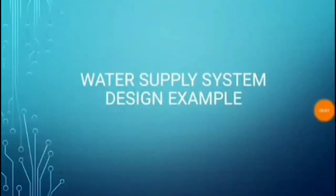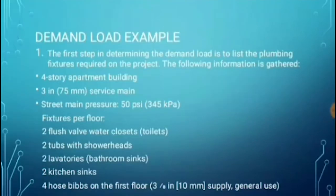Water supply system design. Demand loads consist of three steps. First, we need to determine the demand load by listing the fixtures. It includes a 4-story apartment building, 3 inch or 75 millimeter service main, street main pressure 50 psi or 345 kPa. Fixtures per floor: 2 flush tank water closets, 2 tubs with shower heads, 2 lavatories, bathroom sinks, 2 kitchen sinks, 4 hose bibs on the first floor, 3/8 inch or 10 millimeter supply, general use.